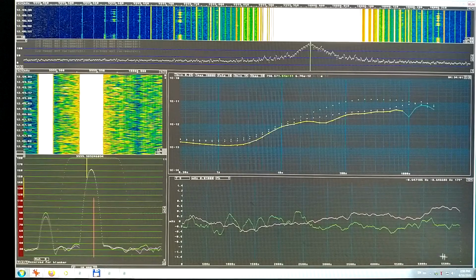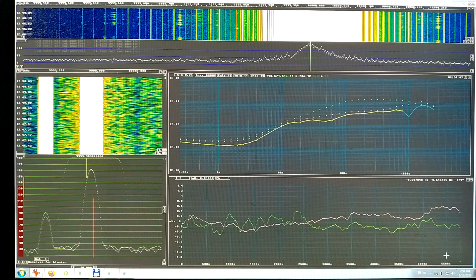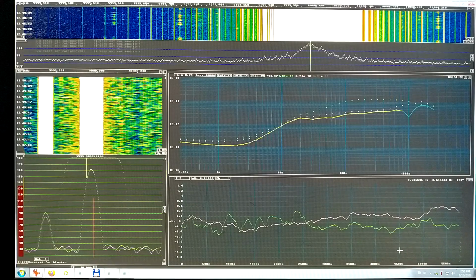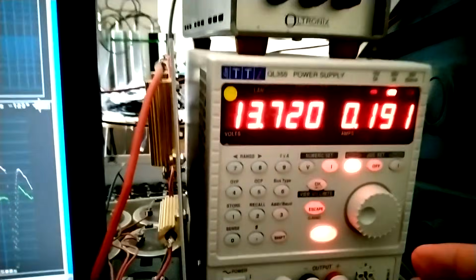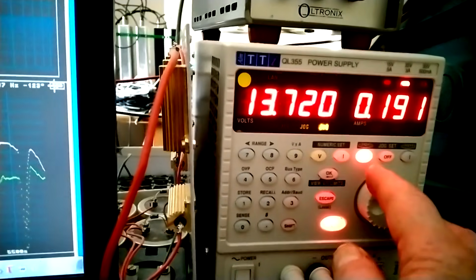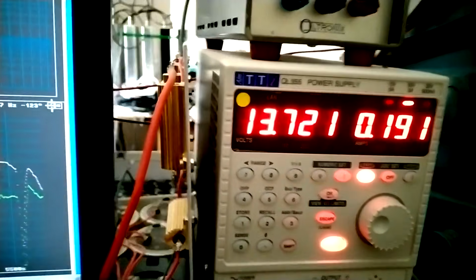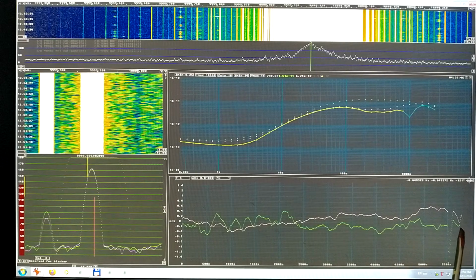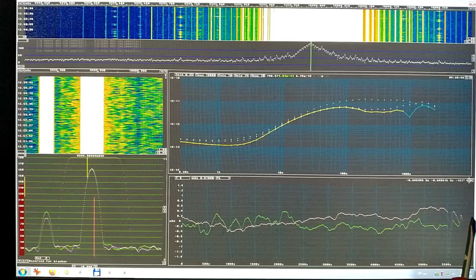Now I plug in the soldering iron here. That has an immediate effect on the frequency, which drops about 1 millihertz. The soldering iron is only 60 watts, so something is changing when the 220 volt supply is changing. I changed this power supply one step, 1 millivolt. This gives a similar response, although much smaller, and this indicates that the soldering iron caused a drop of about 10 millivolts